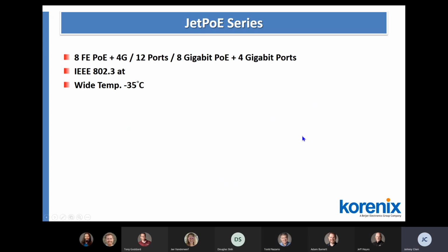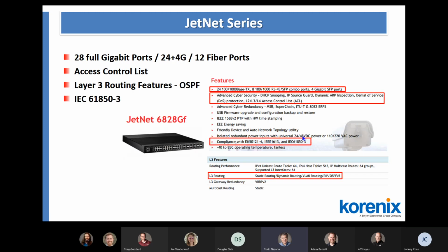Okay, so another question, that switch compliance, does it support certain protocols? I mean, what makes that special for the PT&D industry, power transmission distribution? Yeah, almost all the power stations will request the 61850-3.